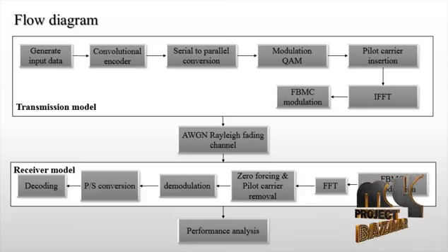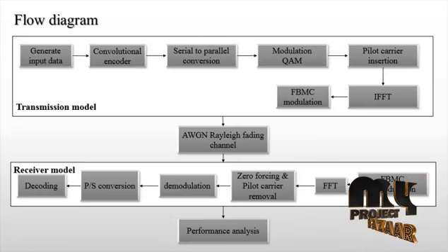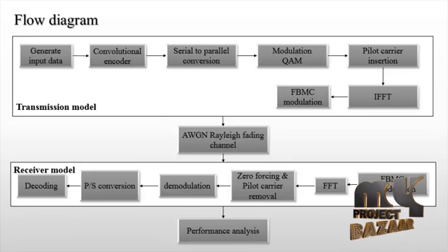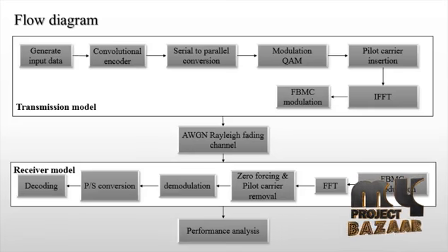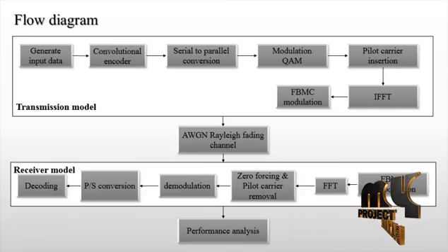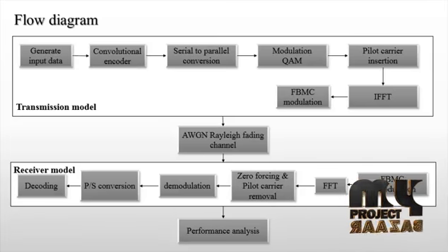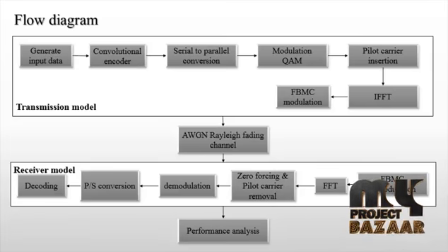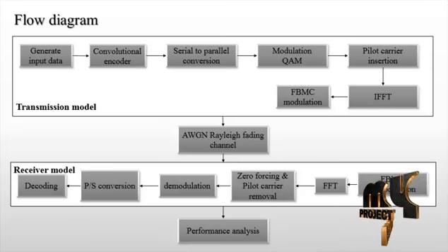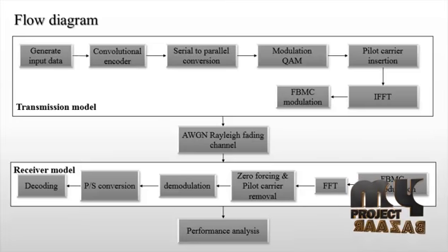The Fourier transform breaks a signal into a number of frequency bands by multiplying the signal with a series of sinusoids. This essentially translates the signal from the time domain to the frequency domain. Then comes the filter bank. The filter bank concept is an array of bandpass filters that separates the input signal into multiple components, each one carrying a single frequency subband of the original signal.